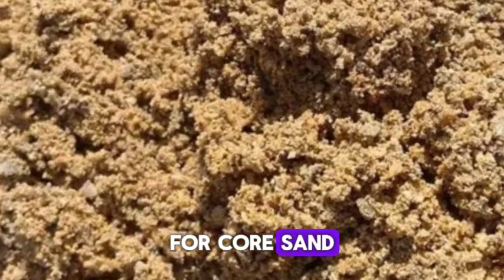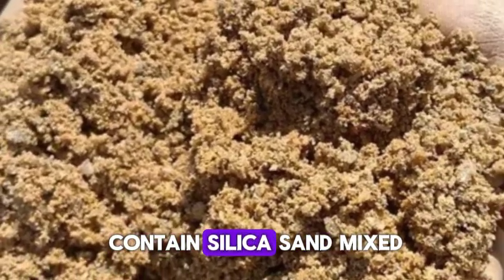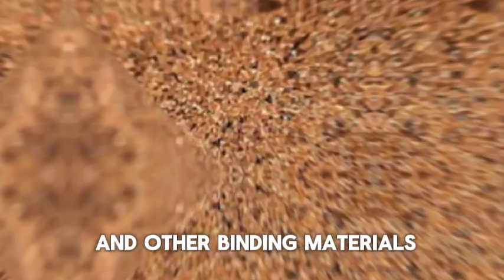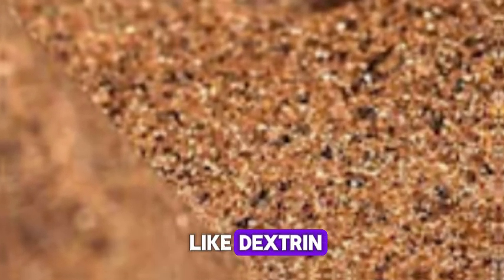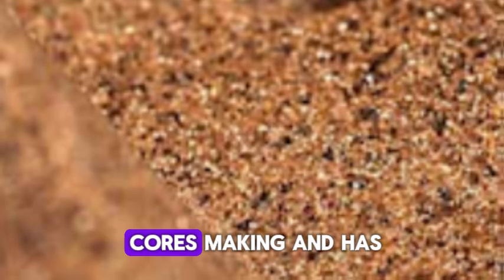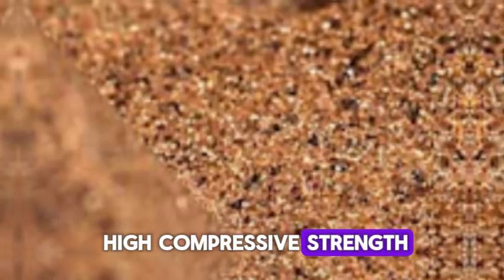4. Core sand. Core molding sand types contain silica sand mixed with core oil, linseed oil, resin, and mineral oil, and other binding materials like dextrin, cornflour, and sodium silicate. It is used for core making and has high compressive strength.